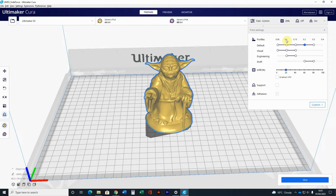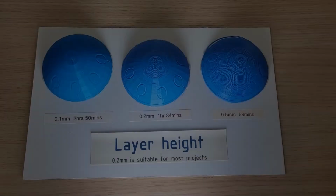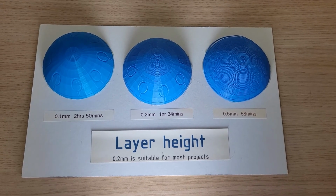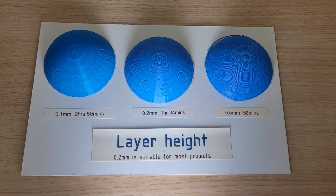So obviously it depends on what you're wanting the print for. These are automatic settings that will set everything up, so it sets visual, takes it to 0.06. I tend to just like to have control and set it myself. 0.2 is pretty standard. Okay, so let's actually have a look at what these layer heights look like in the flesh.